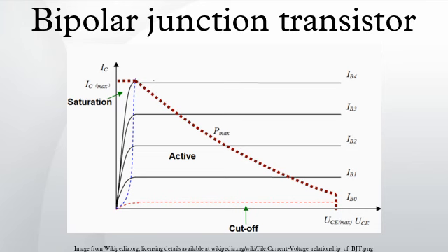This means that interchanging the collector and the emitter makes the transistor leave the forward active mode and start to operate in reverse mode. Because the transistor's internal structure is usually optimized for forward mode operation, interchanging the collector and the emitter makes the values of α and β in reverse operation much smaller than those in forward operation. Often the α of the reverse mode is lower than 0.5.